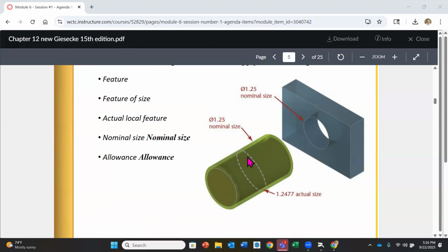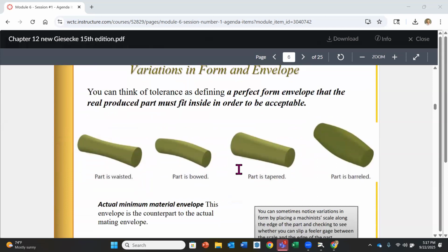Okay. And as we look over its entire length, whatever the tolerance size is, we don't have that information for this particular part. The nominal size is 1 1/4 in this case. And then some sort of a tolerance, whether it is defaulting to the title block or we would have a tolerance specifically in back of it, that would let us know what the limits of size for that outside diameter would be within, okay?